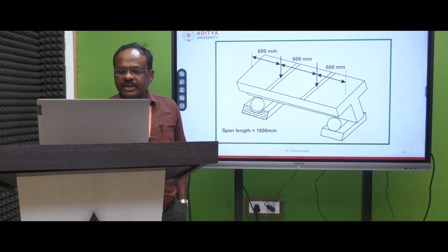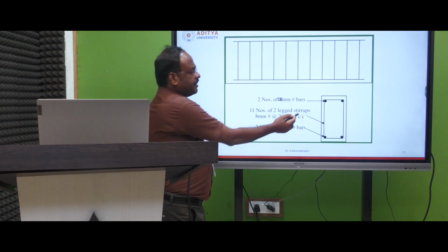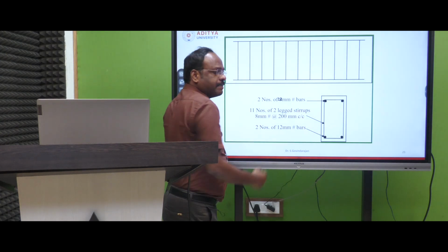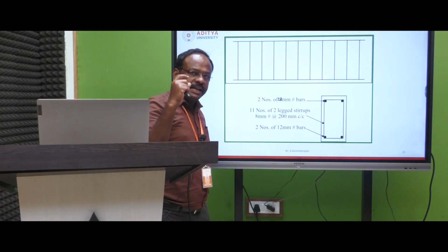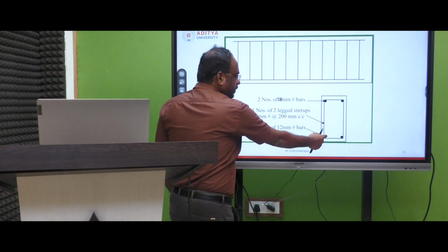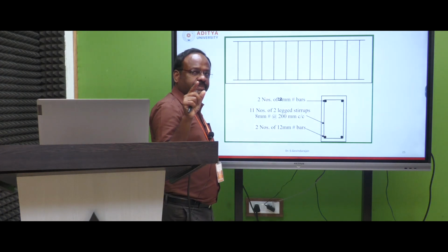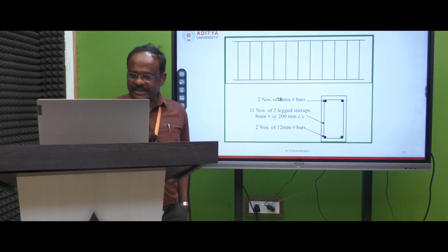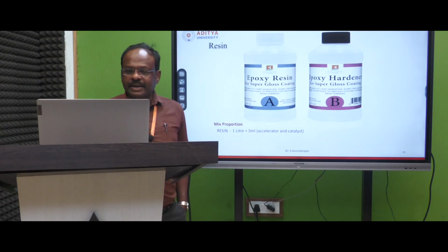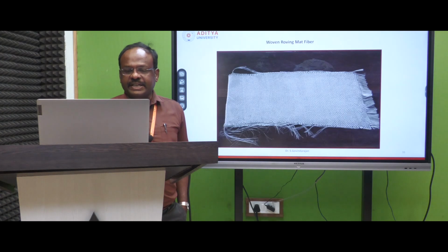For the beam section diagram, I already explained the top reinforcement and bottom reinforcement, where it is located from the bottom at 25 mm clear cover, and from the stirrups. After that you place your reinforcement. So you know where the distance will be. According to that I am going to place the two strain gauges, right?